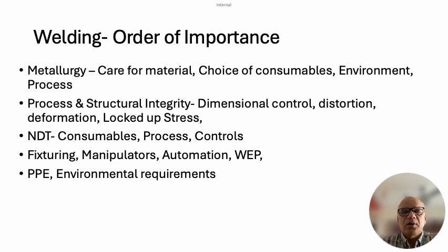Only when all these activities are done has the welding engineer really understood and done his job. So this is only the order of importance, the priorities. In case for a particular metallurgy having complex fixturing, like for aluminium, creating a complex fixture, it being a soft material, sometimes becomes difficult.